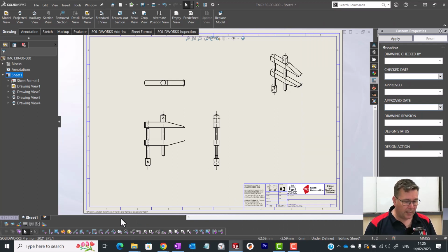So what we want to do here is we want center lines, and we're going to use it so that it only selects center lines. If you ever find that you can't select something, sometimes you've got keyboard shortcuts, and I know E and V are some of them. If I hover over this one, a vector point, if you just press the V, it will turn that on, and it will stop you from selecting lines or faces, but only selecting points. Same here with edges, that's where the E comes into it, and so forth. X is the faces, and again, there's a whole heap of shortcuts that they've got there.